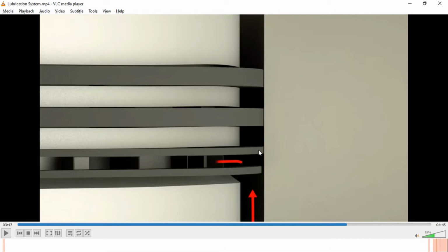This oil ring ensures that all of the oil is scraped off from the surfaces of the cylinder, and some of the oil may get into this section where it will lubricate the crank pin and the small end bearing of the piston. Excess oil flows inwards through holes, especially when the piston is running down. Then the oil can drain down from the piston into the oil sump.